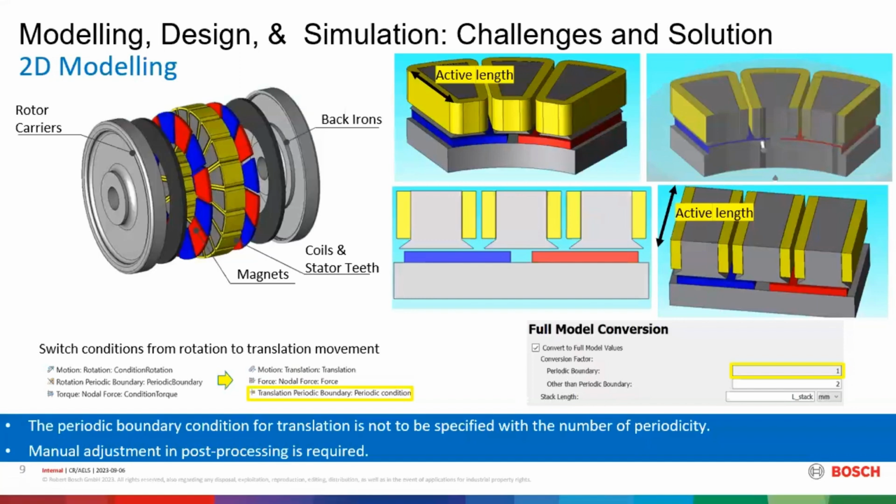condition. And you will often find in literature that a lot of research uses the 2D modeling method for axial flux machines. So if we take a cut plane at the middle radial of this machine, then we will have a curved face. If we straighten this curved face, then we get a 2D model. So indeed, you can model an axial flux machine, at least approximately, using JMAG, just using all the settings for a linear motor.